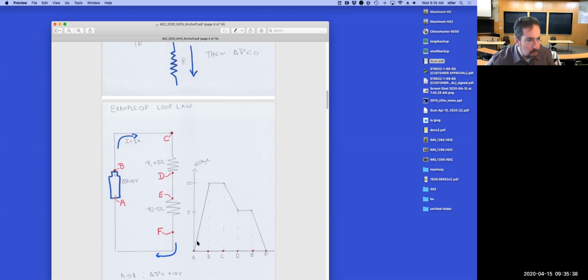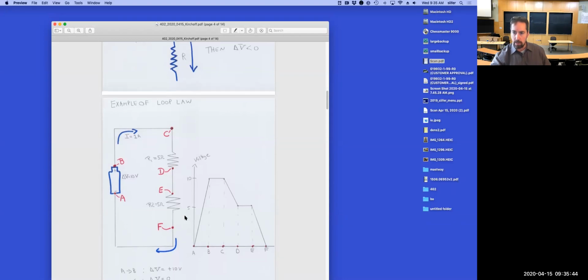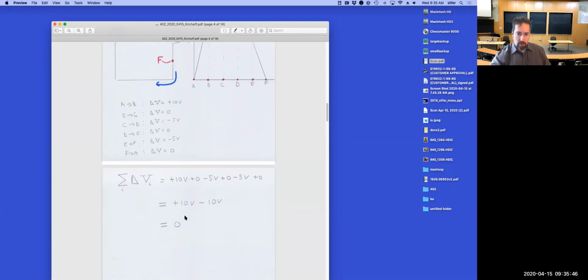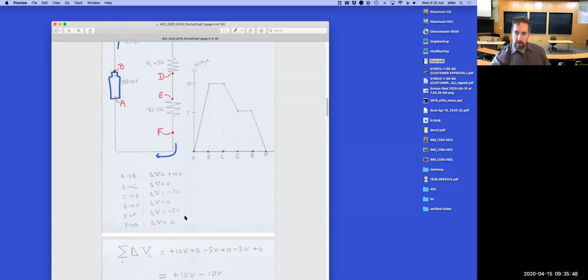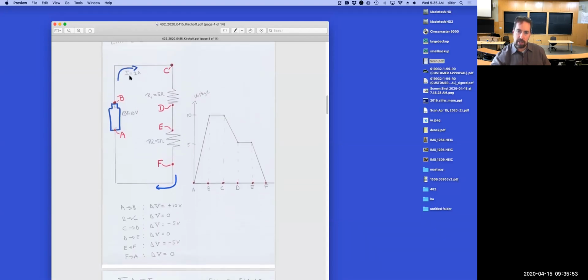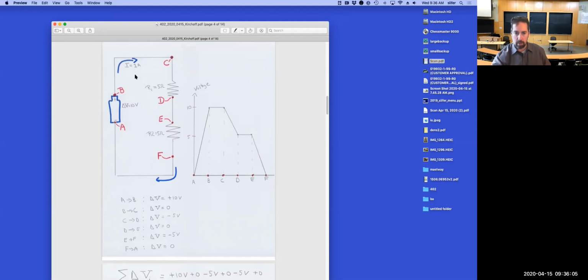Okay, so I hope, Francis, that answers your question, and if not, I'm happy to take another swing at it. But that's our loop rule right there. And again, the subtle part here: if I give you the value of the current, you don't have to make any guess about it. If I don't give you the value of the current, you have to make a guess. But in the end, you would wind up with a negative current, and that's okay. It just tells you that your guess was wrong in the beginning.